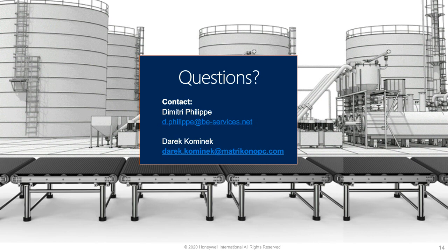Yeah, so good question. One thing with OPC UA is that over time, it will evolve. It has to, because things are changing all the time, especially on the security front. Right now in OPC UA, we've introduced the elliptic curve algorithms, which require less compute power and improve the strength of the security without draining the resources more. So those types of things will continue to happen. Now, they're typically non-breaking. Vendors will have to decide how to navigate that.